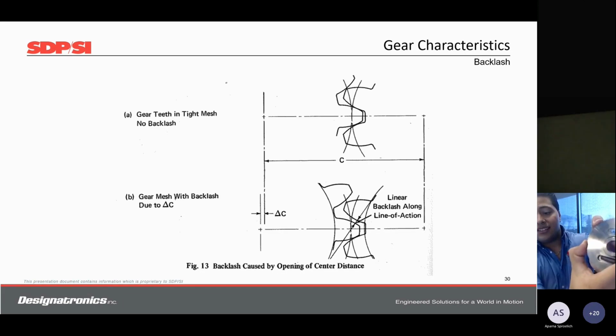Now, one of the drawbacks to this is that the total torque you can transmit will be limited by the torque of the springs themselves. So you won't use the full strength of the gear tooth. This will be a limiting factor for torque transmission. The good thing is for anti-backlash gears, most of the time, you just want them to be accurate and you'll have a low torque application. So this type of gear will work.